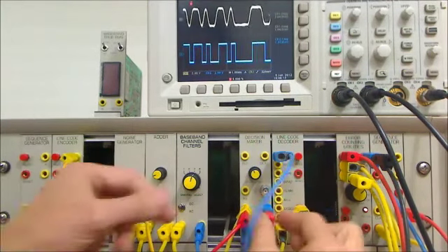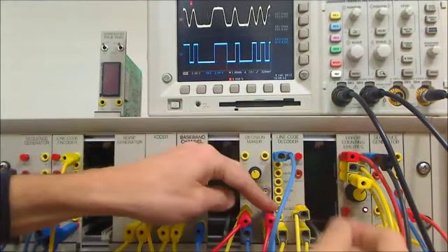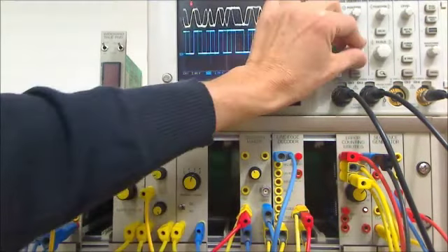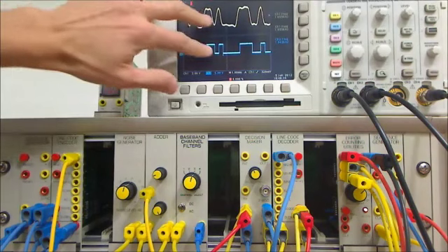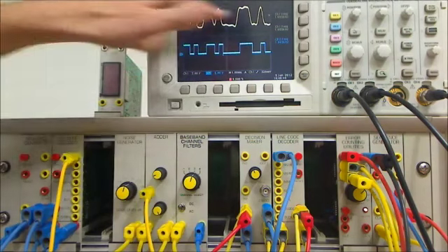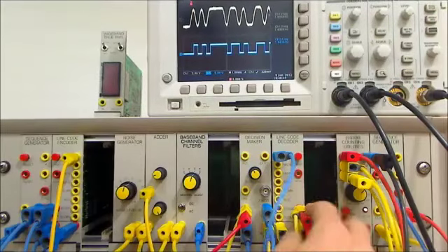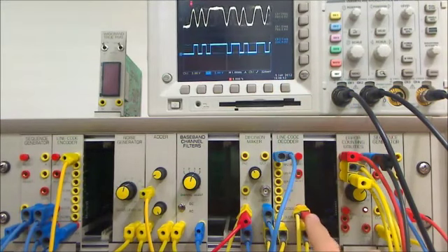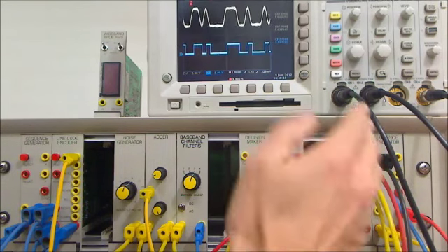So we take that line coded signal, put it into the line code decoder, and out of the line code decoder comes the decoded TTL data signal. You can see once again it corresponds to the signal at the input to the receiver of our system. At this point we now have a TTL version of the received signal. Now what we have to do is count the number of errors in that signal.